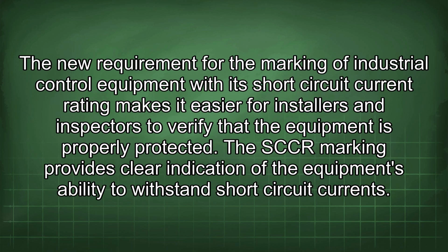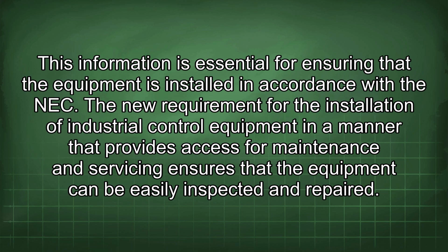The new requirement for the marking of industrial control equipment with its short-circuit current rating makes it easier for installers and inspectors to verify that the equipment is properly protected. The SCCR marking provides clear indication of the equipment's ability to withstand short-circuit currents. This information is essential for ensuring that the equipment is installed in accordance with the NEC.